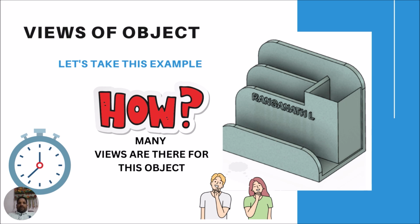Yes, this has 6 views. How many views are there? 6 views are there for this particular object. Let me clarify how I'm saying it has 6 views. It will have a front view: if you are standing here and looking at this object, this is my front view. If I am seeing from the top, it is the top view. If I am seeing from this direction, this is the side view. But which side? If I am standing here, this is my right side, so this will be my right-hand side view. And now, these are the 3 views which everyone knows.